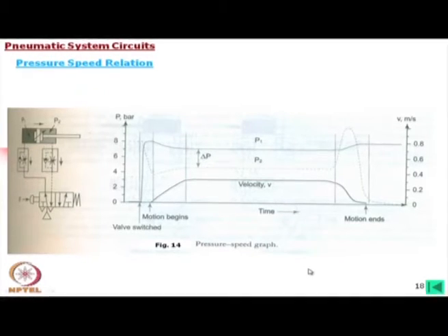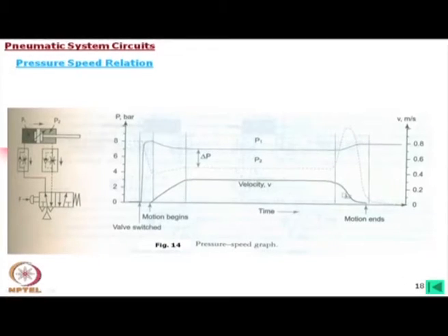Say, for example, we are using this air for some cutting operations, like finishing a plastic, a very soft material, with pneumatics, not hydraulics. In that case, when the tool is moving, we need a constant force, so the operating range has to be within this range. So, knowing such pressure and speed characteristics is important for such circuits. In case of hydraulics, this zone is very small.